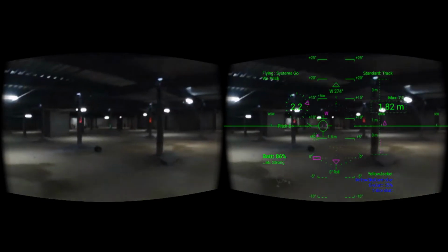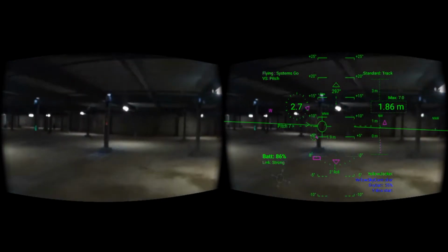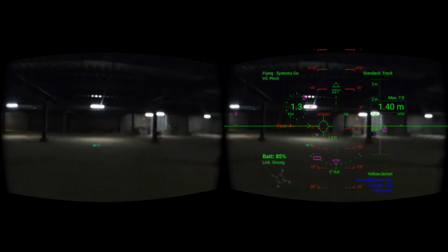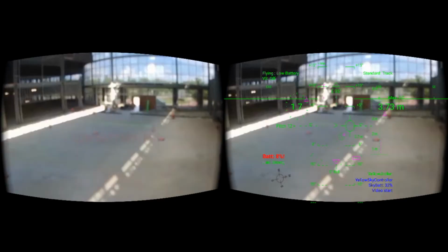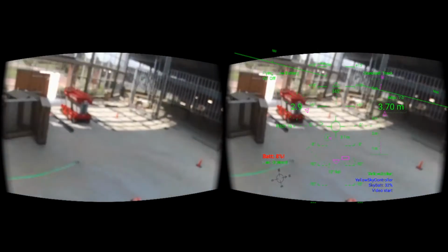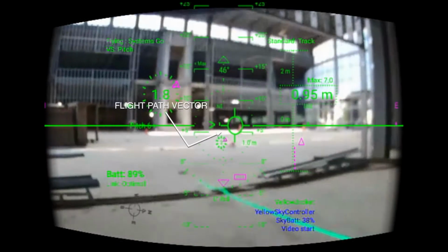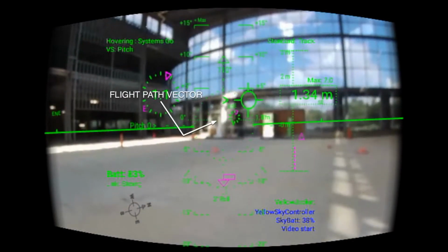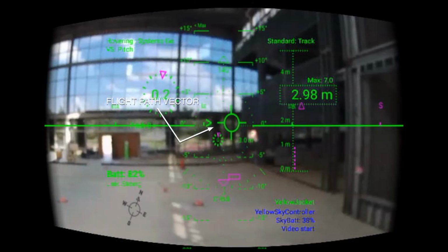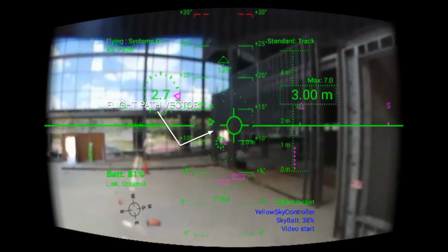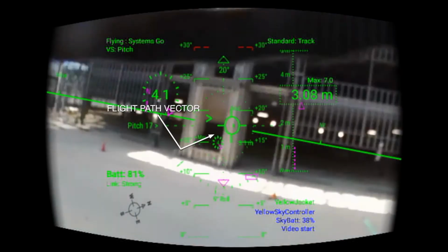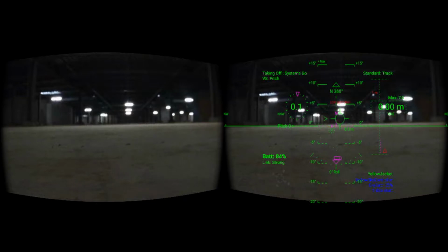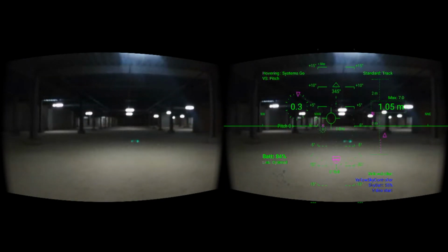In testing, I found through pilot feedback that our pilot's gaze will most likely be closely following one of two things at any given moment during flight: a landmark that the pilot has temporarily designated as a waypoint, or the flight path vector, which is part of the primary guidance information cluster. The flight path vector is also referred to as the FPV. Flight path vector, which we like to call the birdie, gives the pilot about a 1-second advanced estimation of trajectory. This allows her to better estimate where the drone is going to be and gives her additional time to course correct if needed.